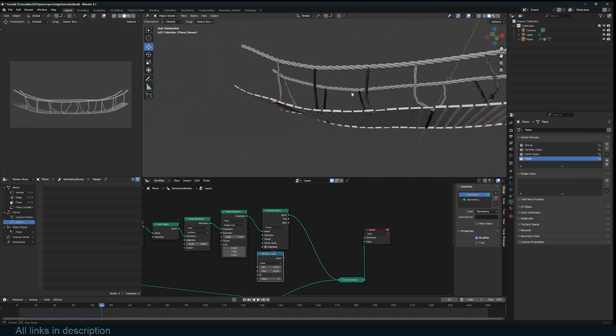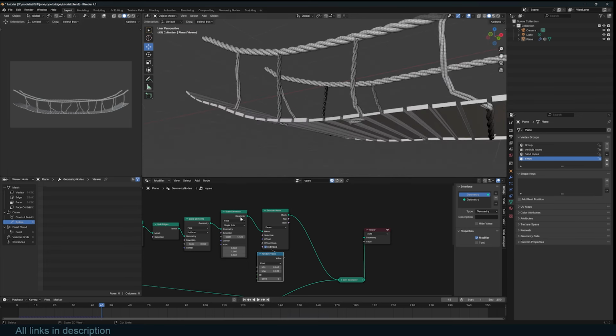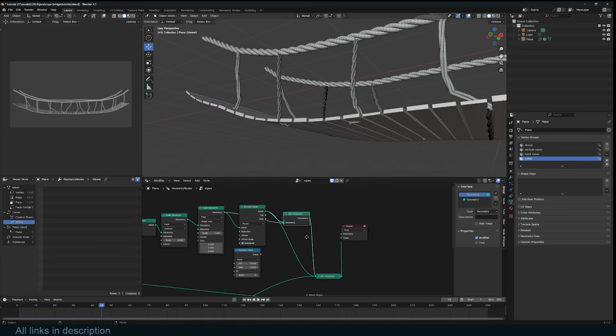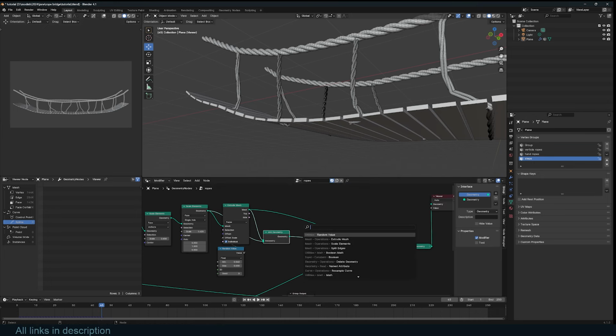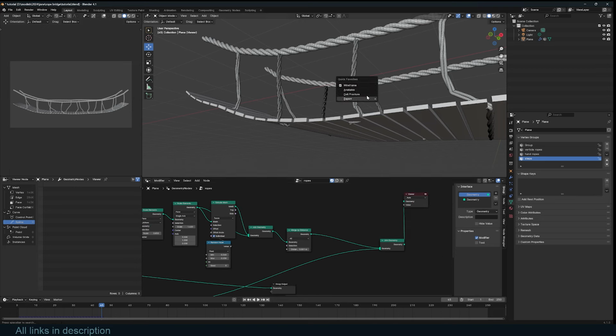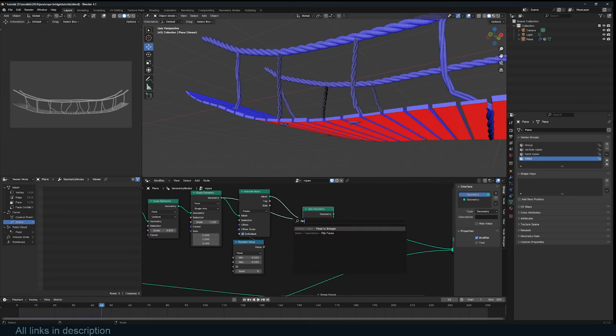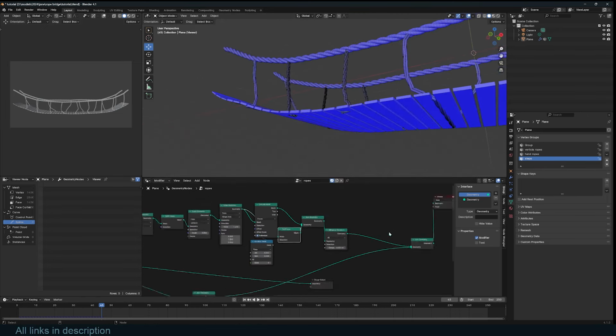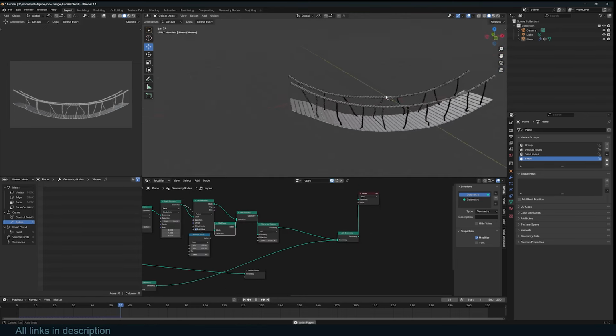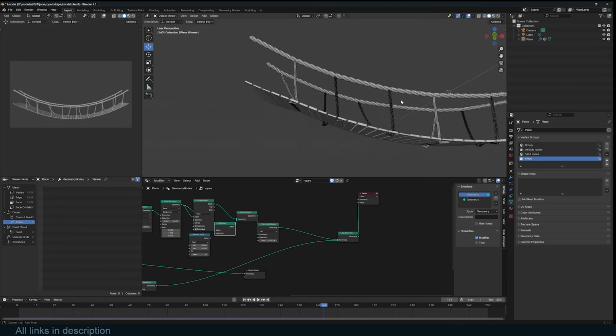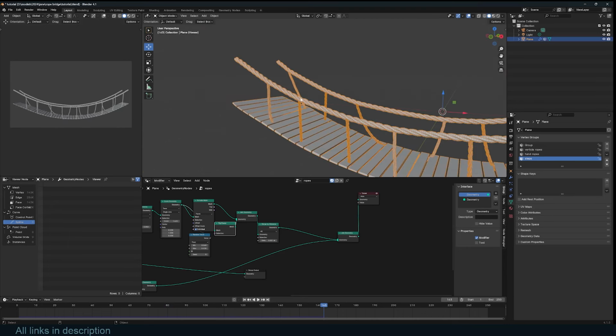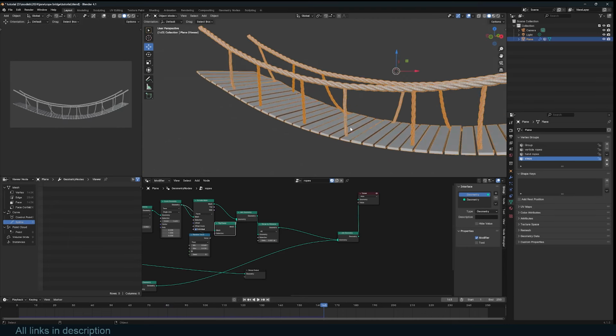If you look down here, you see that we have a hole, so I'm just going to join the original back to the extruded, and we can close that gap. Then I can use a merge by distance, and I can remove this other one. If I look at my normals, you can see I need to flip the original to correct the normals. We have a bridge.